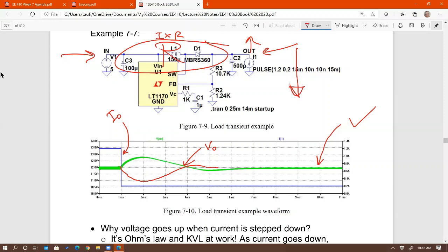Professor, does that make sense? Are you saying that's primarily because of the inductor? No, many things, not just the inductor. The inductor is one of them. We have RDS(on) of the switch. We have the on forward voltage of the diode. So many things, and ESR of the output cap. That's why I'm just going to lump them together into just one R, so that you'll see that between input and output, there's a drop. That's going to be a function of resistance within the circuit.